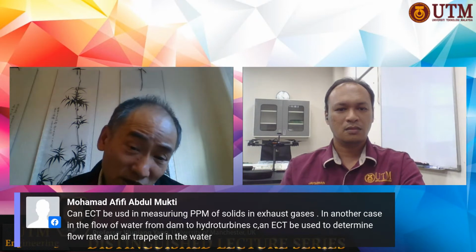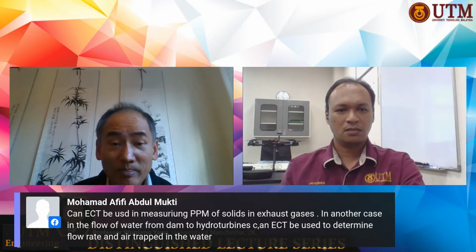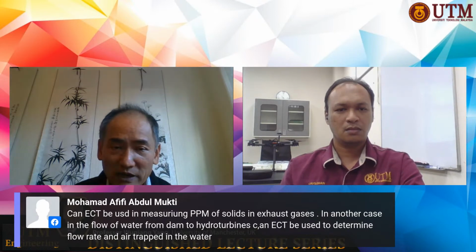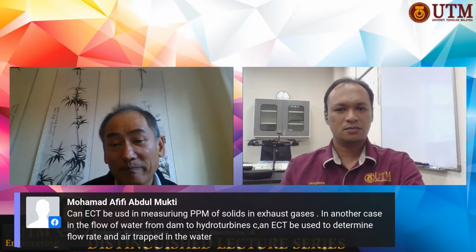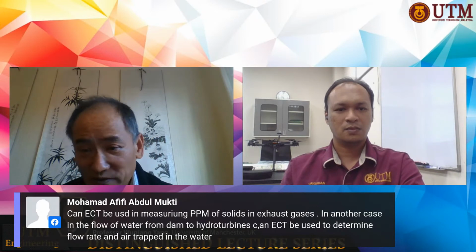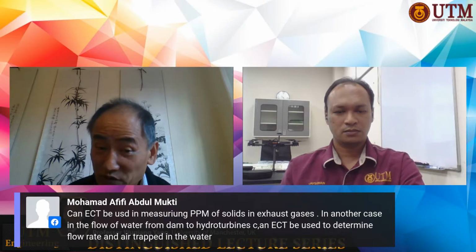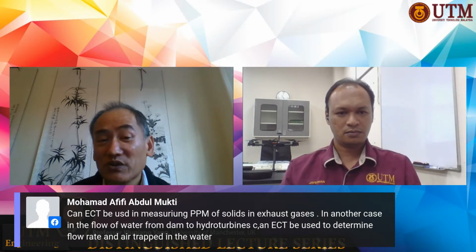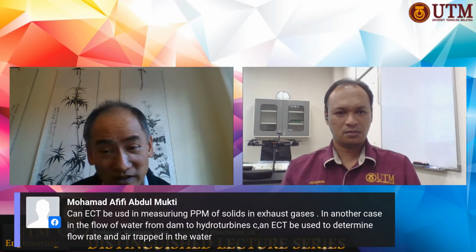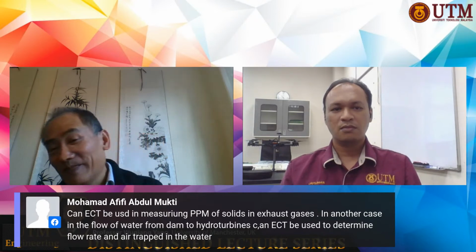The main reason is that in wet gas separation the flow is very, very stable. It wouldn't change quickly. So we can take a much longer time for measurements so that we can manage such lean flow, down to ppm. If we talk about exhaust gas, I guess we can't do it, because with exhaust gas the solid is not stable. It can change too quickly, so you need a very fast measurement. In that case, it is difficult to deal with such low concentration. That is my answer.